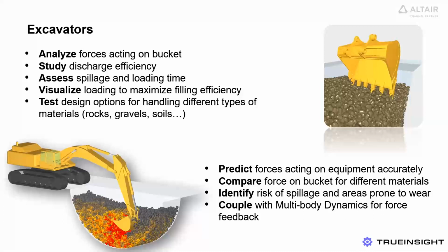As with a dump truck, EDEM allows you to analyze forces during the procedure, and investigate things like loading, discharging, and spillage. You can visualize all of these and test and compare different designs or material options to identify the areas prone to things like spillage, material buildup, and wear. As buckets can have quite complicated motion, you can couple to an MBD package and allow those packages to control the motion whilst still experiencing the forces from EDEM.